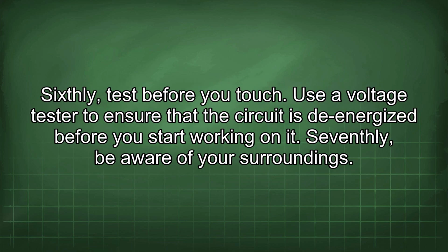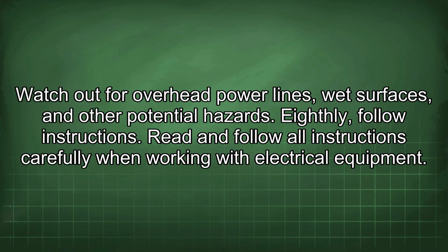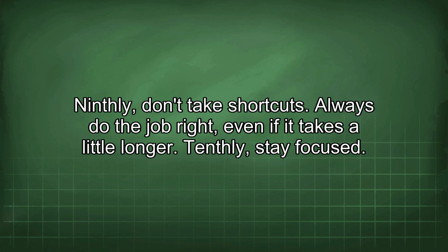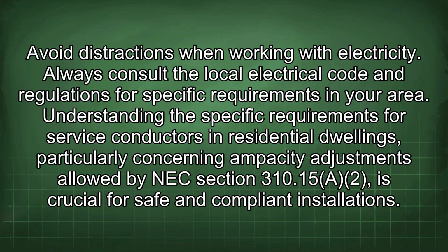Use a voltage tester to ensure that the circuit is de-energized before you start working on it. Seventhly, be aware of your surroundings. Watch out for overhead power lines, wet surfaces, and other potential hazards. Eighthly, follow instructions. Read and follow all instructions carefully when working with electrical equipment. Ninthly, don't take shortcuts. Always do the job right even if it takes a little longer. Tenthly, stay focused. Avoid distractions when working with electricity. Always consult the local electrical code and regulations for specific requirements in your area.